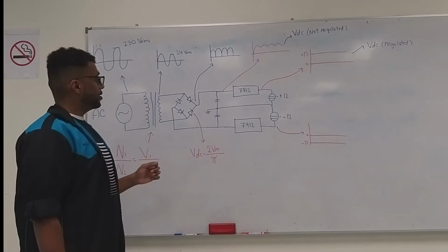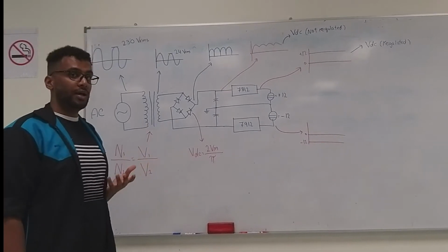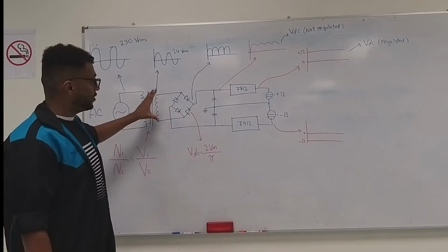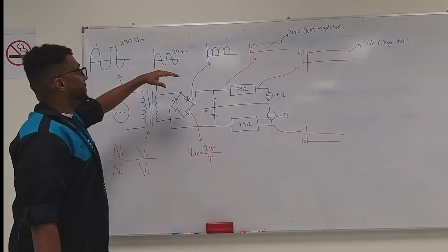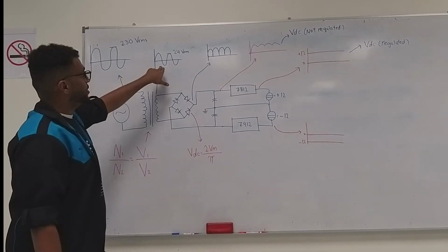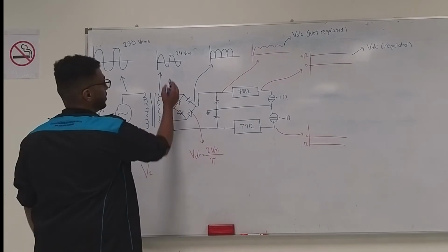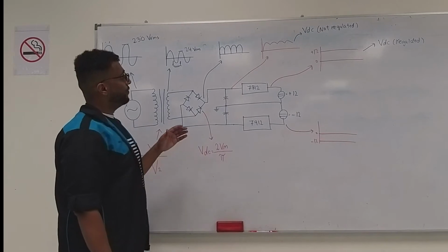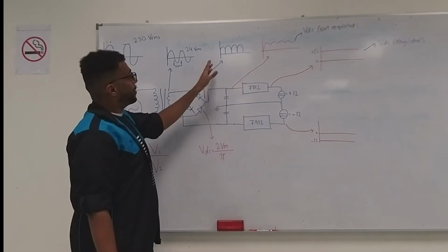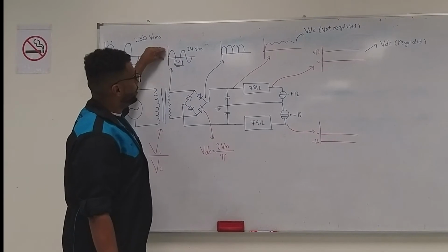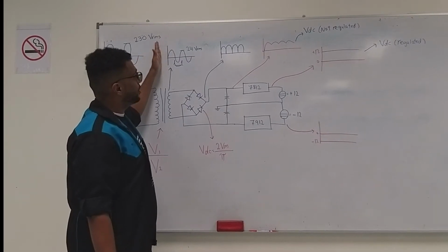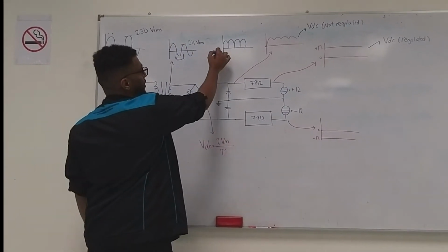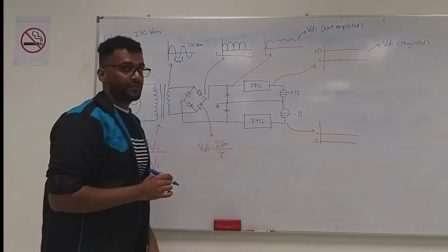So next, we connected the transformer with a full wave rectifier, meaning that we used 4 diodes in this kind of connection in order to cut the lower part, this part exactly. We want to remove this one. The effect of the full wave rectifier is that the upper part of the waveform gets repeated, and this is the output for the full wave rectifier.